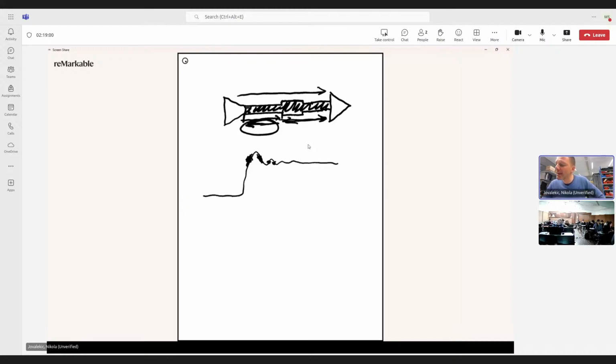You will control the impedance, and it means that you will control the geometry of the trace. So you will have a constant width of the trace. But what happens here? You cannot just route straight lines. You need to go here. Then you will have some small discontinuity at this point, but this is inevitable.